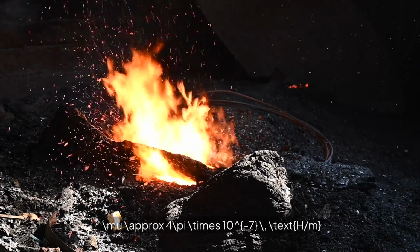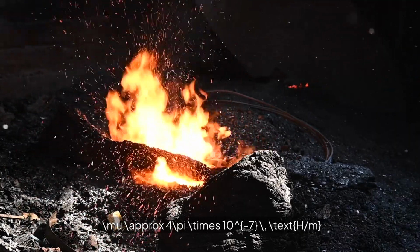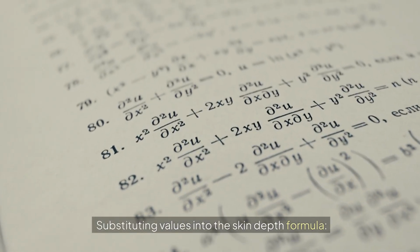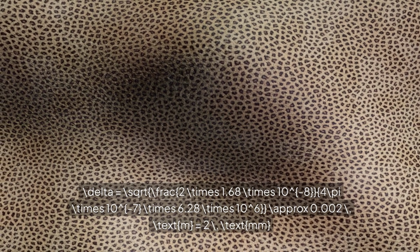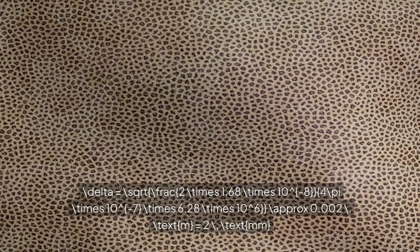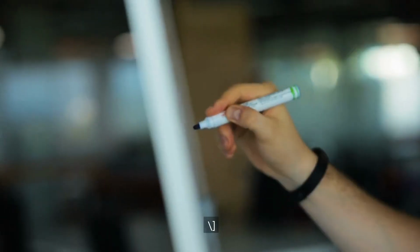Therefore, mu ≈ 4π × 10^-7 H/m. Substituting values into the skin depth formula, delta = sqrt(2 × 1.68 × 10^-8 / (4π × 10^-7 × 6.28 × 10^6)) ≈ 0.002 m, or 2 mm.